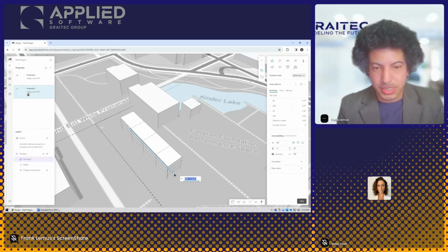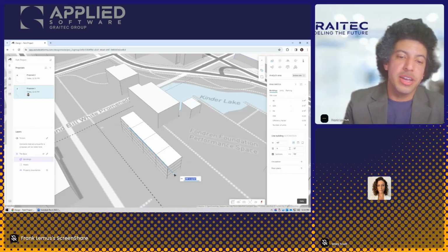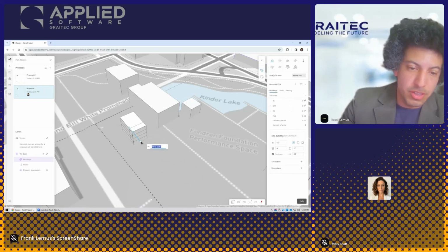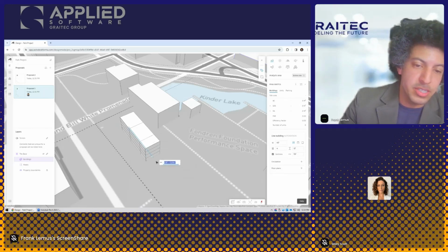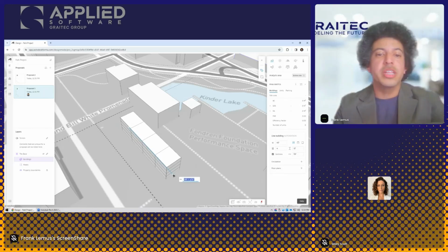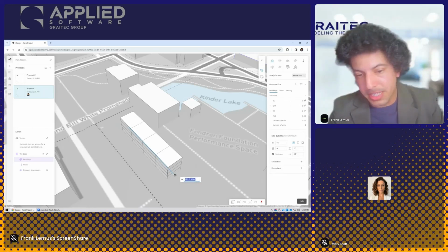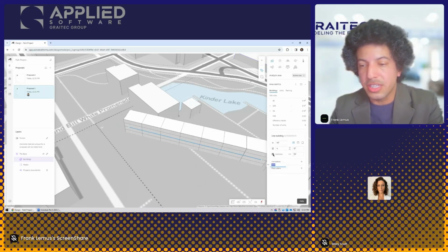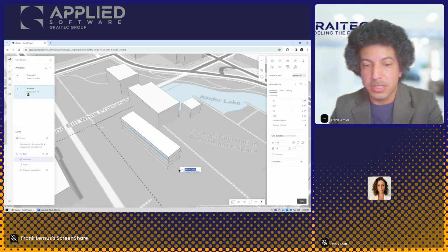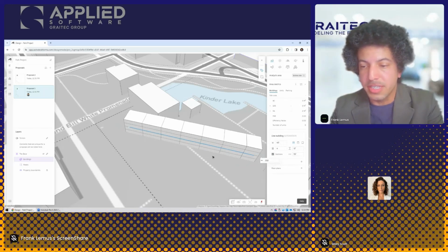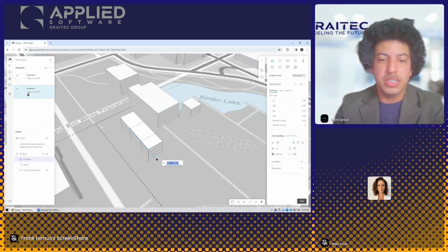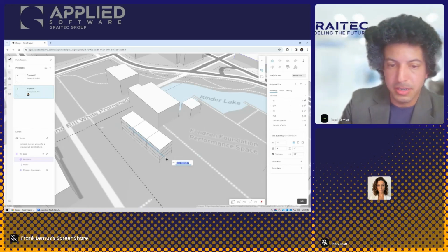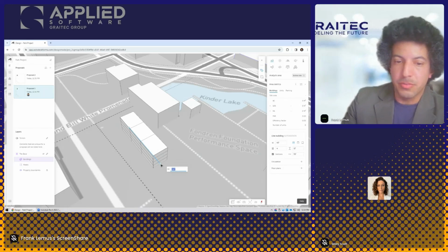Really, the reason we would do this is because after we create our line item, we may want to have modular control just of this first section, the floors on that first section. If we didn't have sections, it would just be treated as one big thing. Maybe that's not what you want. If it isn't, you could change that. You can say, don't give me sections, so just one big thing, or yes, give me sections. It's not referring to sections that you might see in document development when you're in Revit.